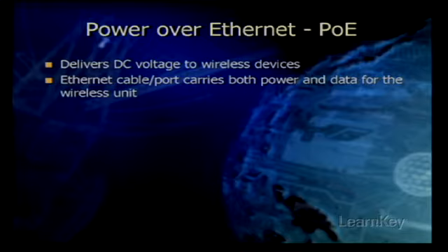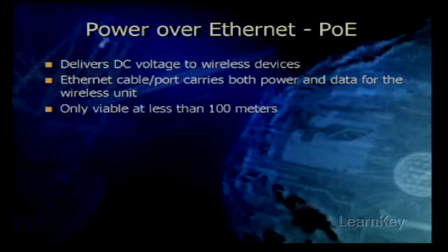The labor costs that would be incurred to install electrical outlets throughout this ceiling would definitely be high. Hiring an electrician as well would be expensive and very time-consuming. So, we can use Power over Ethernet to solve this type of a problem. One thing to remember about Power over Ethernet, however, is that Ethernet cables only carry data reliably for 100 meters. And for any distance more than 100 meters, Power over Ethernet is not going to be a viable solution.